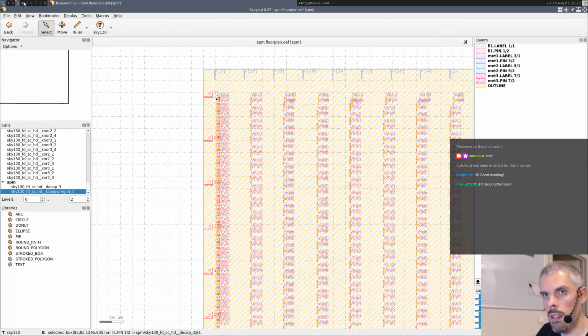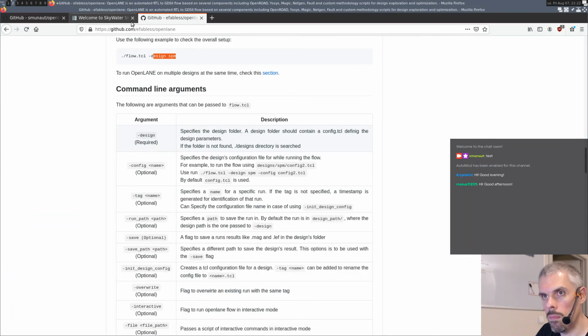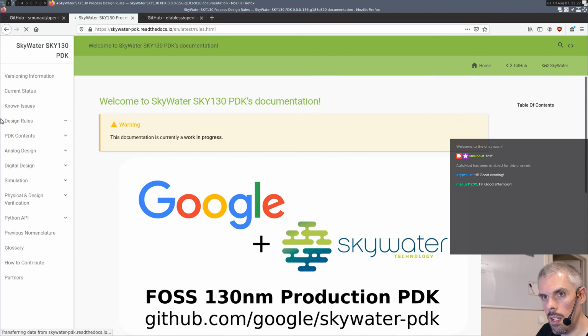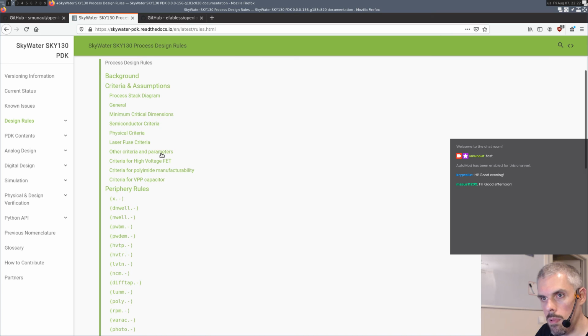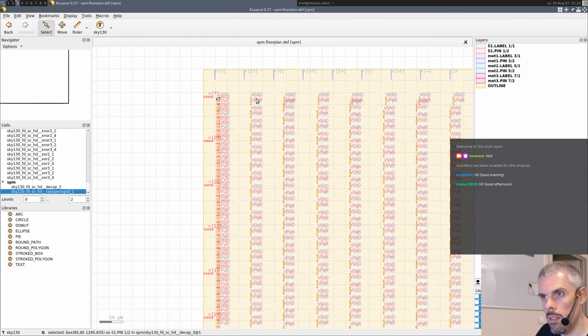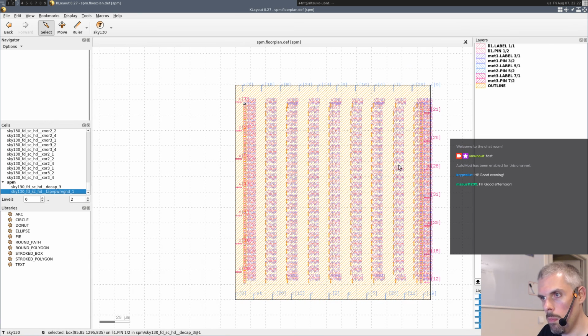The PDK, the DRC rules, the design rules, I don't remember exactly where, but they specify that there is a maximum distance between any transistor and one of those special tap cells that bias things properly for things to work. And so here, the first step is distributing them on the chip, basically.